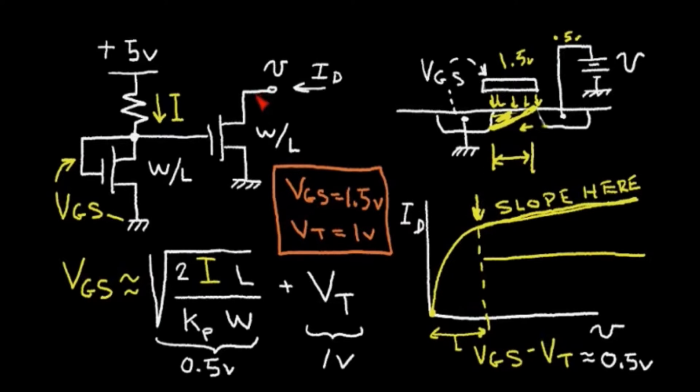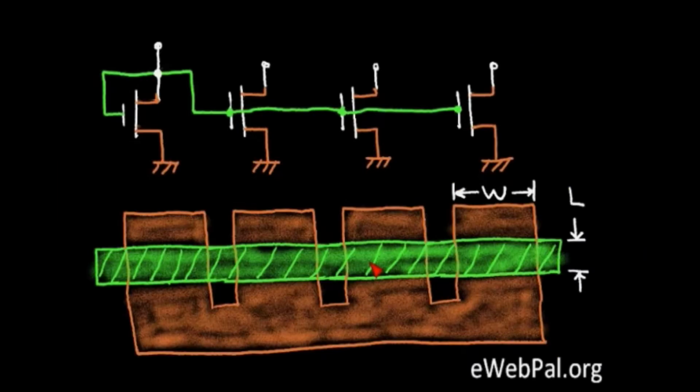So now let's look at how we would do the layout of this particular set of NMOS transistors. This shows a typical layout for this current source. Now here I've added 2 additional N-channel transistors. So this part is our original current source that we examined previously. Now below I've shown the layout, and I've kind of color coded this. So the green is the gate electrode.